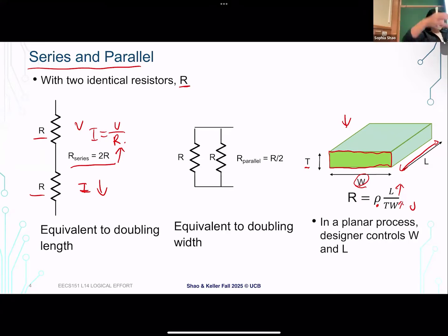And when we put things in parallel, right? So now if you think about the current flowing through this, the overall resistance actually decreases. Again, the current can go through this path and this path, so the current actually increases, because now we have parallel paths. For this scenario, we have smaller resistance, higher current, and a stronger circuit or stronger gate that's better at driving and charging and discharging the downstream gate, right? Make sense? Just a quick review.